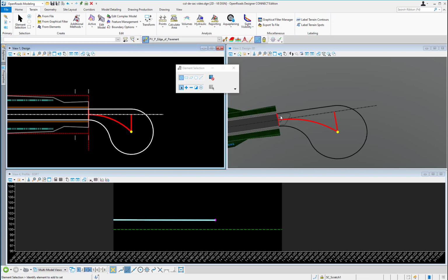So now you see a couple contours were created, but we need to go ahead and add in this last arc as our break line. So we'll add a feature, select our terrain, and then locate the break line. So there our contours look nice and smooth like we would expect.